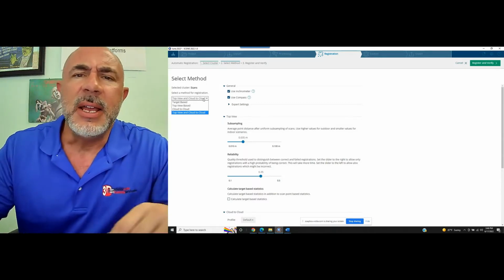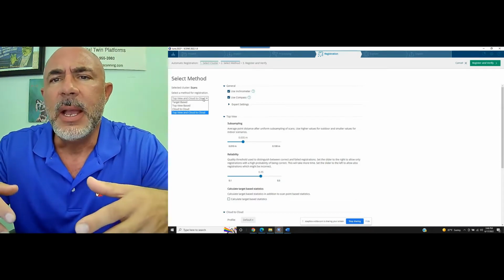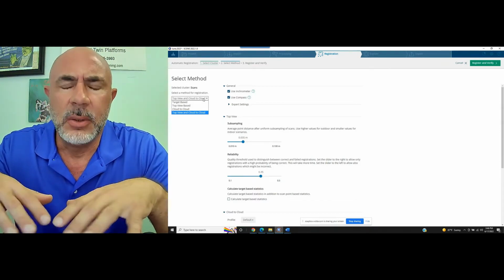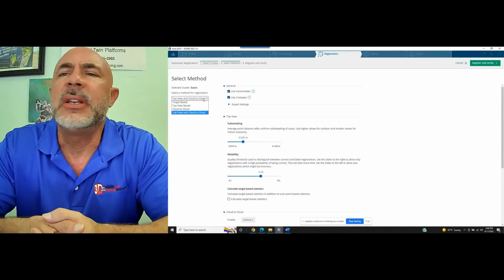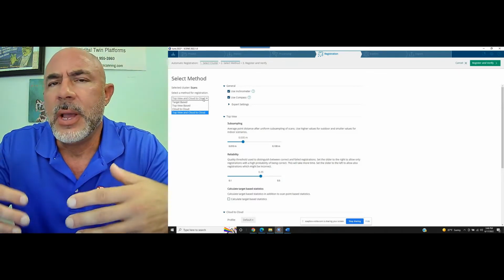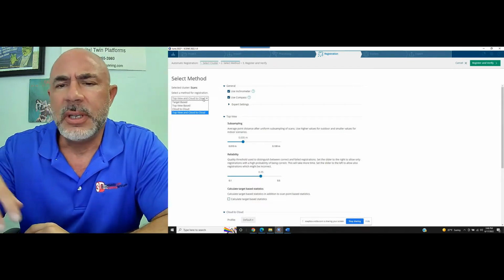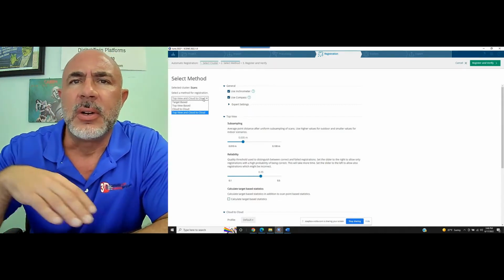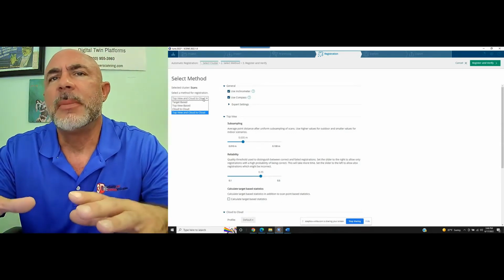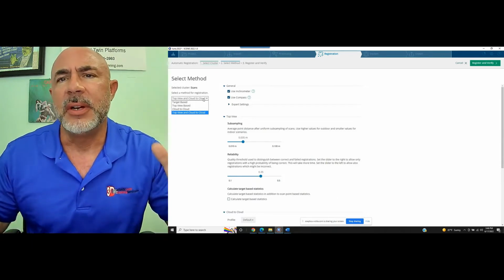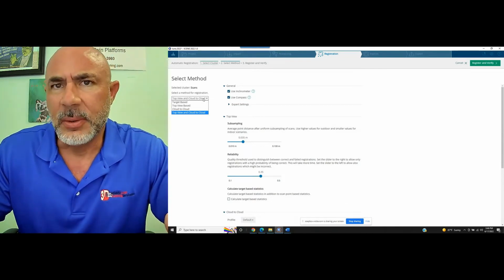What FARO does is it's going to take the scans, say scan 1 and scan 2, and if you are in an area, hopefully, that has geometry. So if you're going to be, in this case, scanning the side of a building, any interior or exterior of a building or a piece of equipment that is stationary, when you work the scanner around it, there is going to be geometry. There are going to be corners in geometry of that piece of equipment or that building that are stationary, and that they're going to be used for registration points by the software.